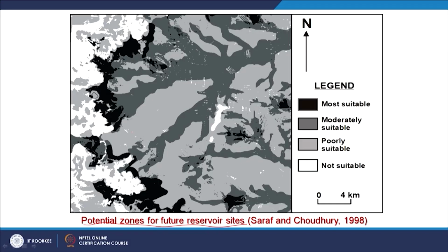So, these are the areas, the black ones are the most suitable, not at the same level, but a little higher, and not so much higher that the watershed becomes small. So, just at the edge of those higher grounds, because we have learned through that blue reservoir, the Sironj reservoir, that if it is located on high ground, it will have a large benefit area relative to submerged area. So, that knowledge we developed, and based on that knowledge we can develop such maps.